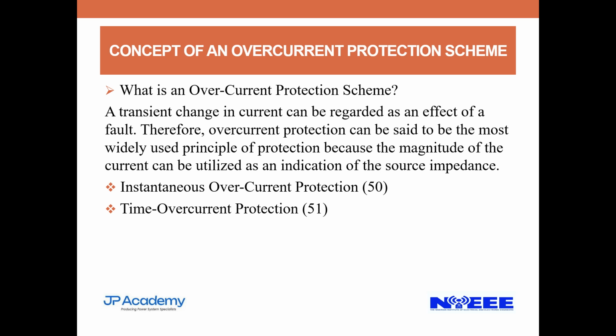And it operates on the principle of measuring the input current, then comparing it with the output current, Kirchhoff's current law. Once there are discrepancies, then it knows that there is a fault. That is the principle of operation of the differential protection scheme.